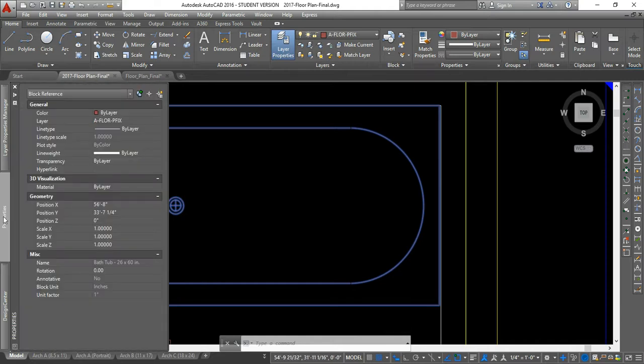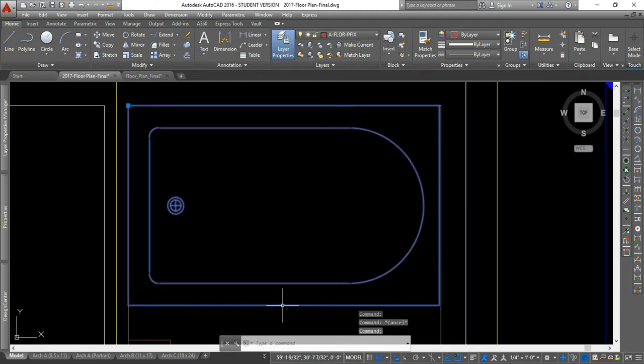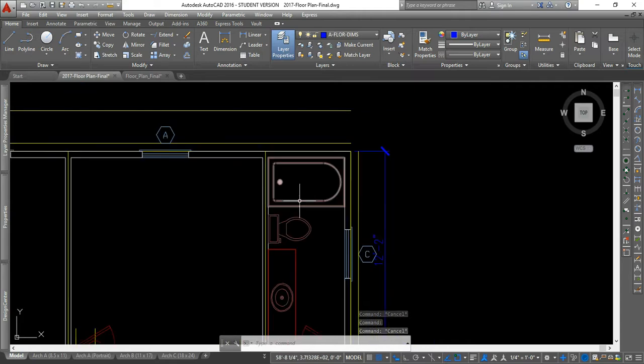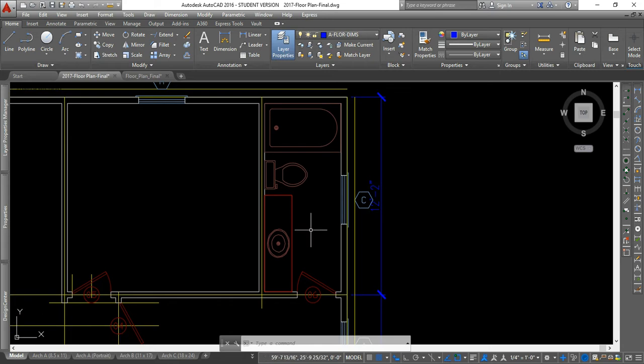If you bring it in from the design center, you'll have to explode it and resize it to fit it in there. Watch out for your spacing between it and your toilet, and toilet to the cabinet. We covered that back in the section on the living spaces and serving spaces. The cabinet length and size should be a standard vanity type cabinet.